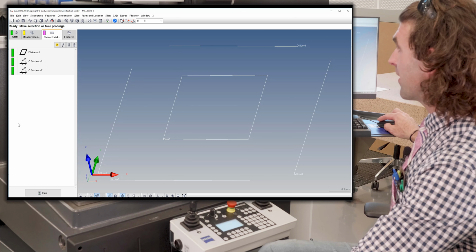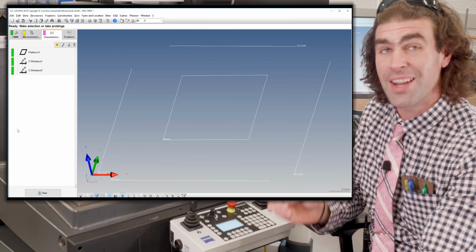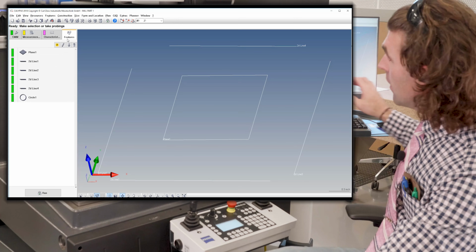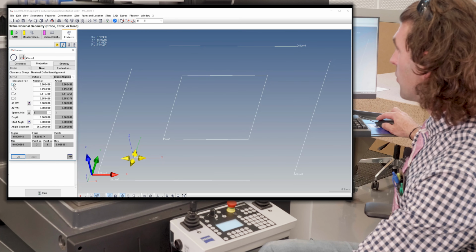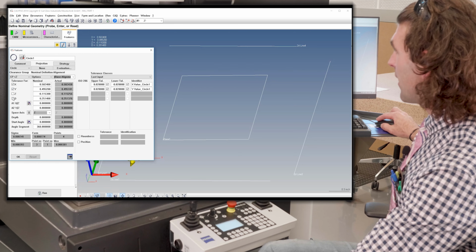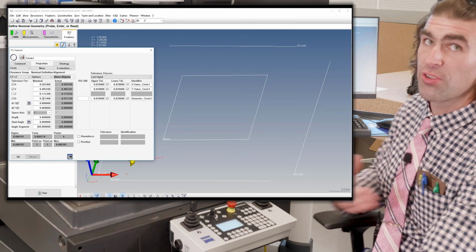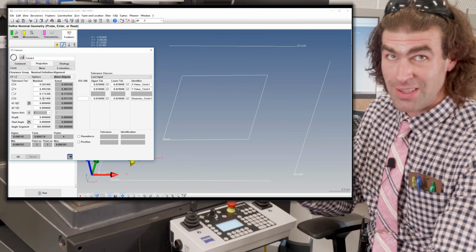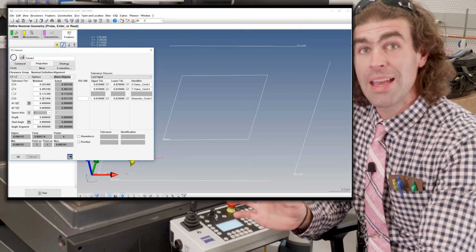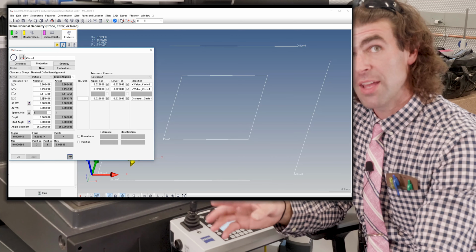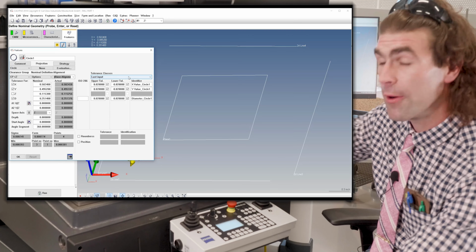I'm going to go to the characteristics tab. If you notice, there's no diameter or X and Y for the circle. It's not outputting anything to the report. I want to go to features. I'll go back into this circle, hit the pen tool. I want to hit this X checkbox, this Y checkbox, and the D checkbox. So D stands for diameter, X is the distance in X, Y is the distance in Y from the origin that we established in our alignment, which should match the origin of the drawing, okay? So it's this bottom corner of the part.